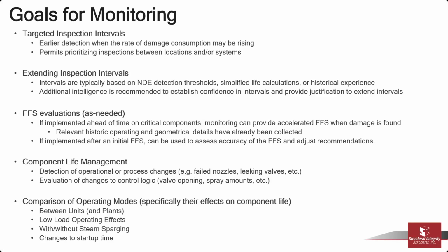So one thing I'm excited about is just finding problems quickly. As I mentioned earlier, if something broke, like an attemperator nozzle, or if you had poor control logic, for example, and you were getting some weird differentials downstream of your attemperators, you can pick up on it very quickly, and you can go in and address that issue as soon as possible or during your next planned outage.